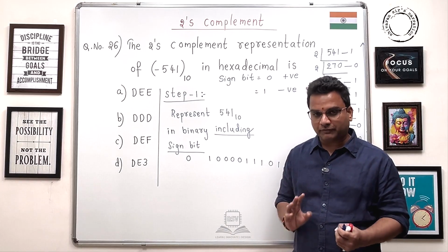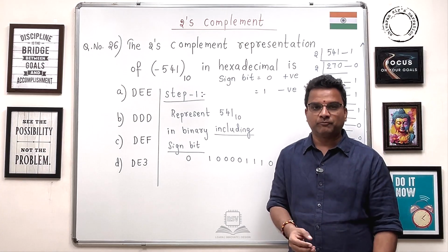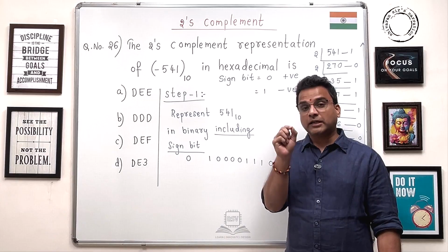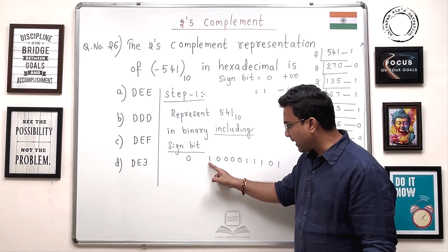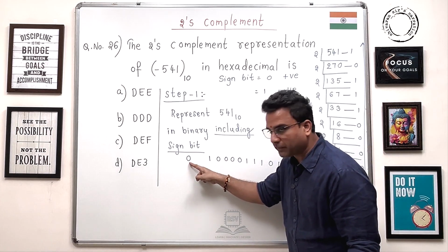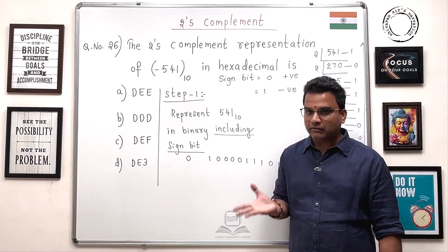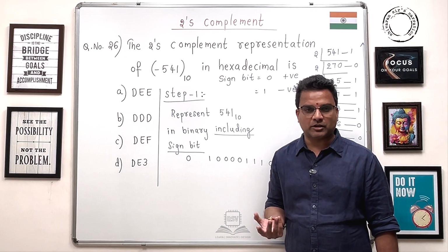Hence, we have to see how many extra bits we require, and place that many zeros between the sign bit and the magnitude bits. This is the magnitude bits, this is the sign bit. Here we have 11 bits but we want 12 bits. Then how many bits do you require extra? 1 bit.